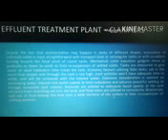Effluent treatment plant, the clarifiers. Although sedimentation may happen in tanks of different shapes, removal of collected solids is most straightforward with conveyor lines in rectangular tanks or with scrapers rotating around the central axis of circular tanks.